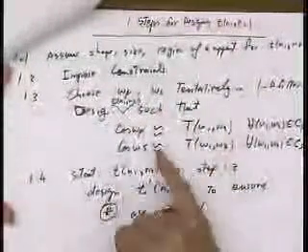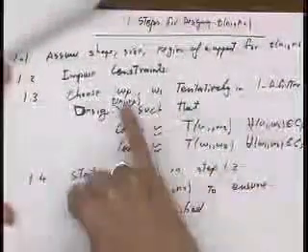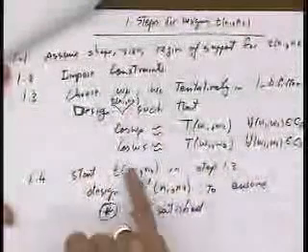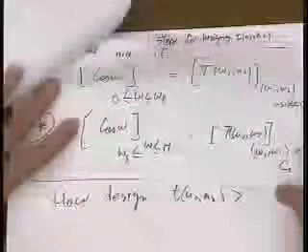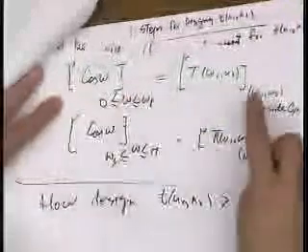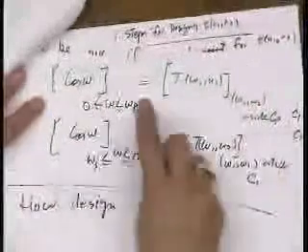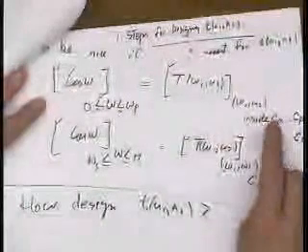Once we have a tentative design for T, we massage it a little bit. We refine or tune it up. We change T to T prime such that these conditions are satisfied, such that for omega between 0 and omega p in one dimension, you want that range of frequencies to get mapped into the region inside C sub p, the passband contour, for our final filter.